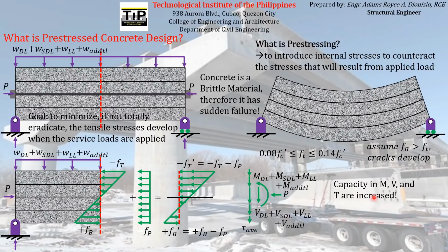And then, actually, the pre-stressing what we did here is actually called linear pre-stressing. Yung addition natin ng pre-stressing reinforcement dito, that kind of pre-stressing is called linear pre-stressing. So why is it called linear pre-stressing? Because the pre-stressing force is applied parallel to the axis of the member. So obviously this is the pre-stressing force, and it is parallel to the axis of the member or the concrete beam. So if that is the case, we can say that this pre-stressing is a linear pre-stressing.